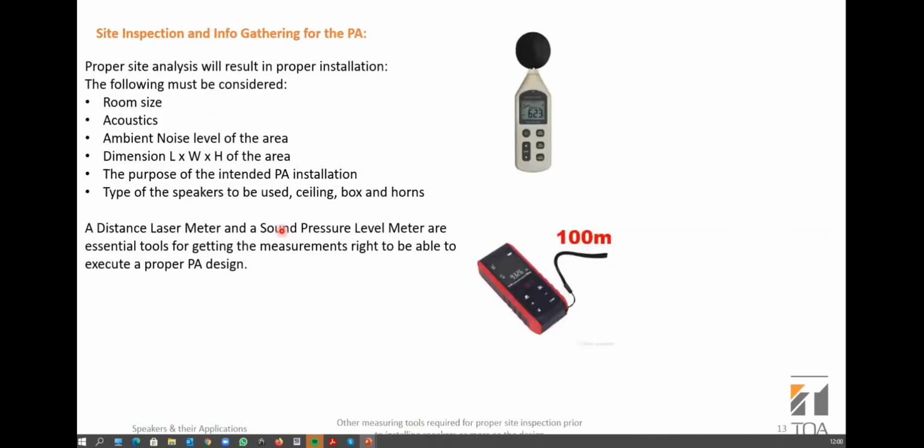Right. So for technical work, when you are working with any site, please always have these instruments. We all work differently, but you must always have an SPL meter. You cannot design a public address system effectively if you don't know the existing noise that is sitting in that particular area. You can also have a distance meter. You can use a tape measure if you want, but you can also have a distance meter.